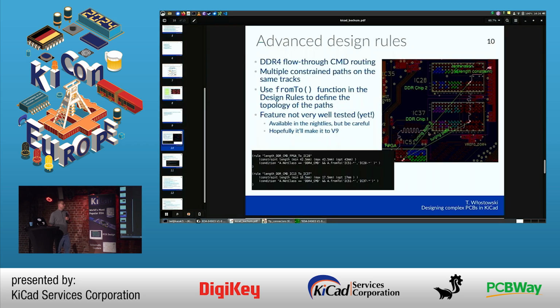What's next? Boards with FPGAs and high-speed memory interfaces usually use DDR3, DDR4, DDR5. This requires a bit of signal integrity, in particular length tuning. Not as hardcore as many people would imagine; length matching down to 0.01 millimeters is futile, but plus minus a few millimeters is a desirable goal.